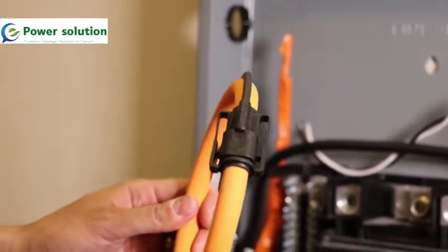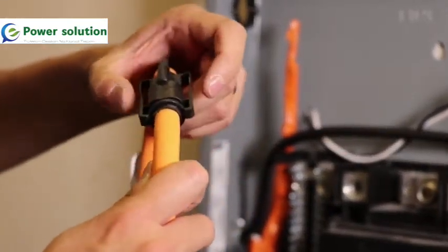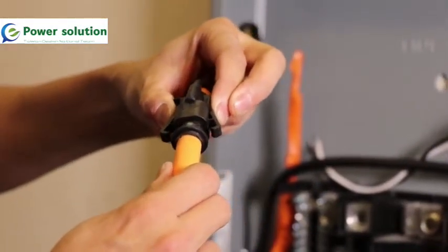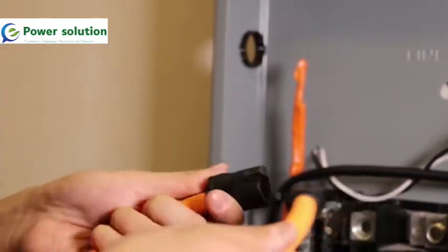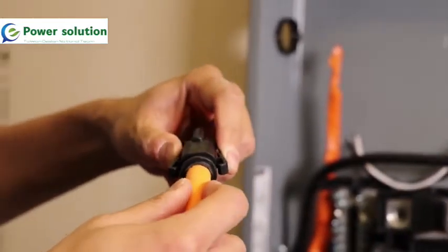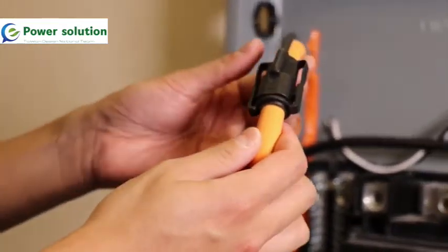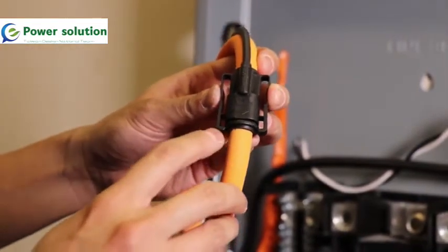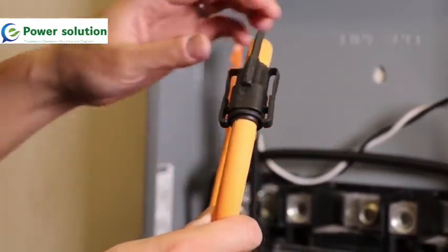Our system is also compatible with an AccuEnergy Rogowski coil. The coil opens by pushing these two tabs in to unlock these clasps, and the coil opens this way. Many people prefer this because it's flexible and can fit in tight spaces. The Rogowski coil is good for any load above 600 amps, up to almost 20,000 amps. When installing, the coil also has a designated arrow that shows the direction of the current, so you want to make sure that current is flowing this way through the coil when installed.